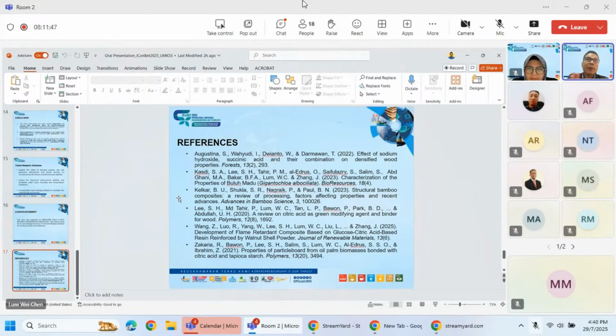For urea formaldehyde particle board, the allowance for the particle moisture content is higher because the solid content for urea formaldehyde is normally higher. In our case, we have a lot more water in our citric acid adhesive. The viscosity is also lower compared to the urea formaldehyde adhesive. So that's the reason, in order for us to avoid delamination, we need to dry our particles to 3%. The maximum is 5%. So this is to answer your first question.